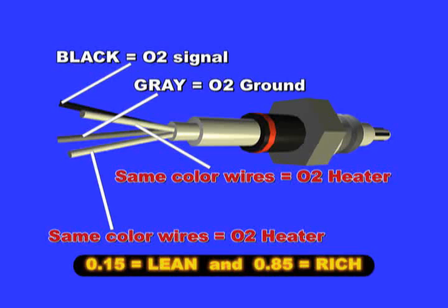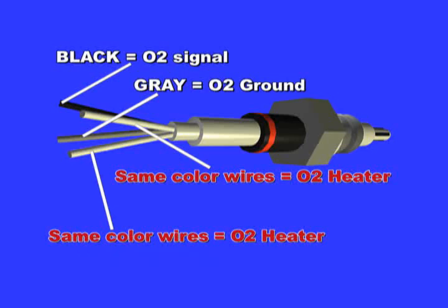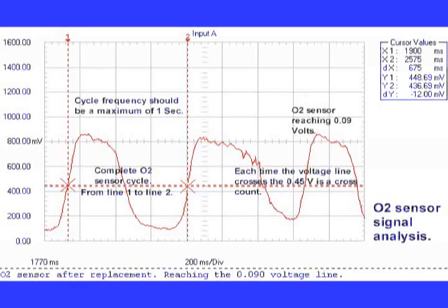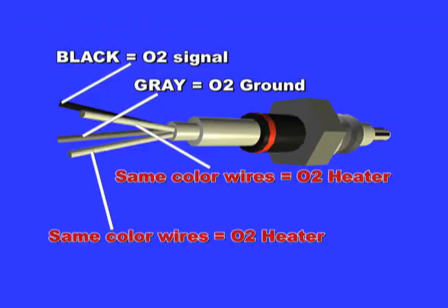In actuality, the O2 sensor should always be changing from 0.15 to 0.85 volts every second. This corresponds to a frequency of 1 Hz. A graphing meter, such as the ADP Scope 1, is preferable to view this signal directly. You may also use the graphing feature of the ADP Scan 1 Pro to view the O2 sensor waveform.